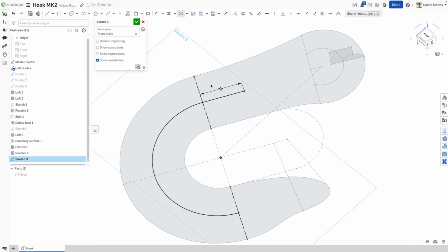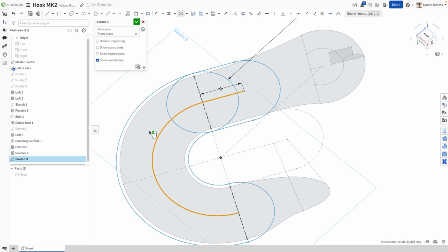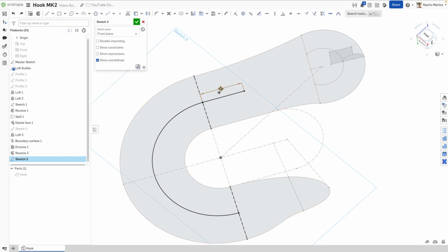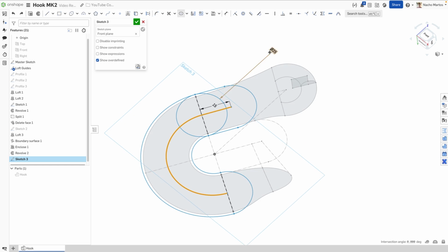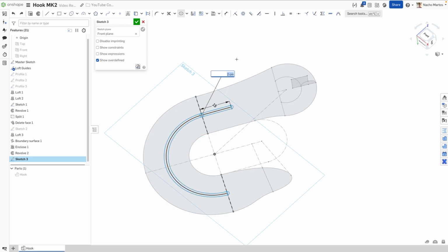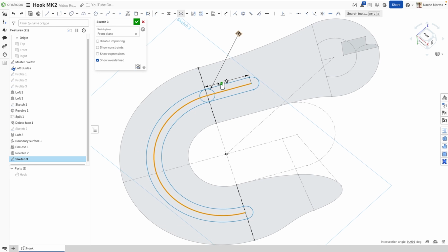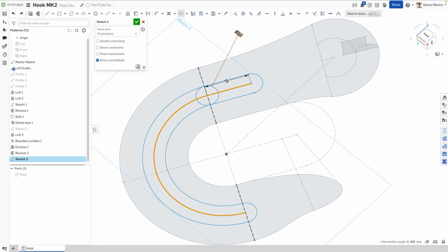Now selecting the slot, we want to create 2 slots. We can make this whatever dimensions. Whoops, that's definitely the wrong dimension. Let's try that again. So we want to select slot. And here we go. This is what we're after. We can make this whatever dimension we want, and it's just going to be some detailing for the sign. So I'll go with 7.5 centimeters. We can commit that slot.